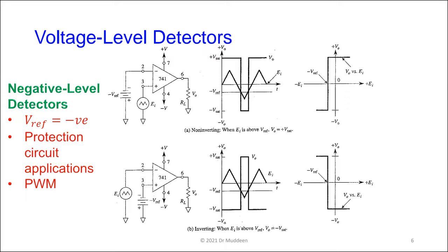I don't know how many of you have, for instance, appliance voltage detectors in your house. What the appliance voltage detector does is, if the voltage is, let's say, between 105 and about 120 or so, everything is all right. But if the power dips or goes above that, the device switches off. You'll hear a click, and the power is disconnected until the power supply regularizes itself, and then you'll hear the relay click again, and it comes back on. Those use voltage level detectors.